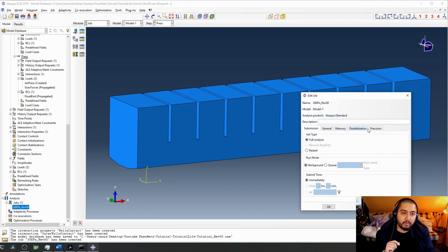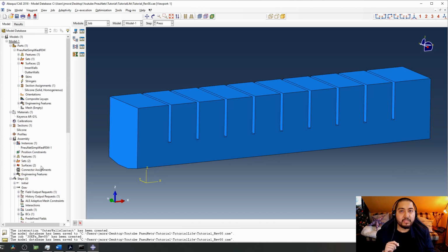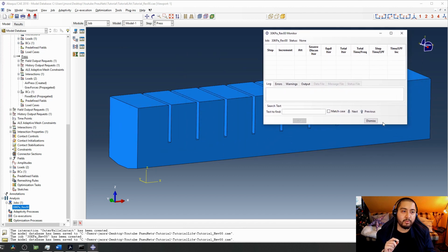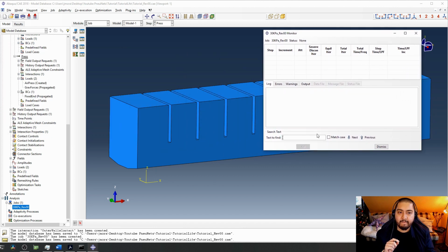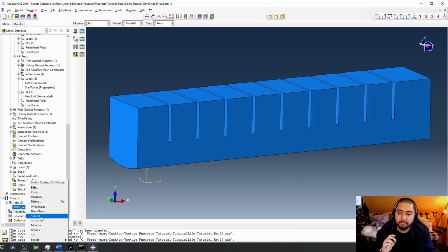If we click on the job, we can go again to the properties that we defined. And I can really recommend you to save it again before running something. If we made no mistakes during this tutorial, or if you get an error, you can go back to see the chapters that I'm going to define for you in the video, and then take a look at what is probably wrong. And then I always recommend to monitor the solution. With the monitor, you can see the status of the running job. And then let's press submit.